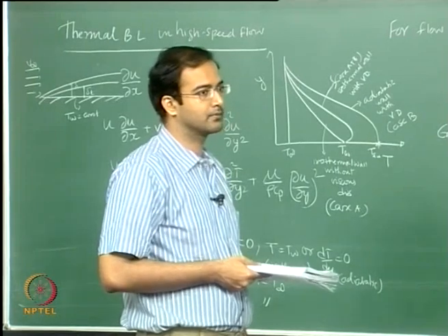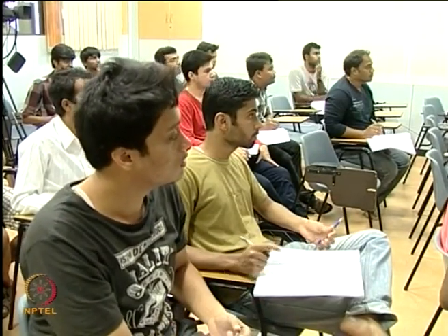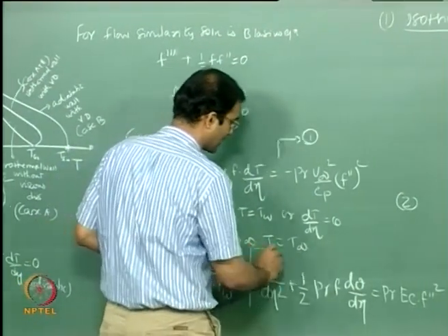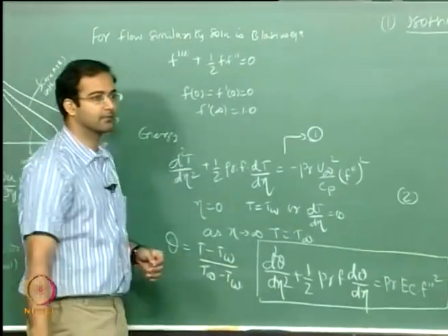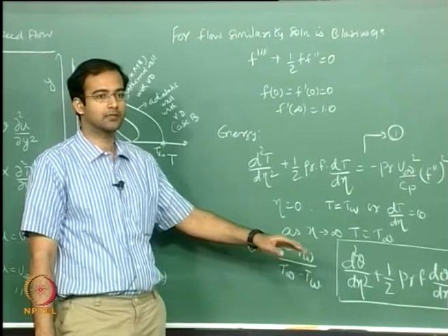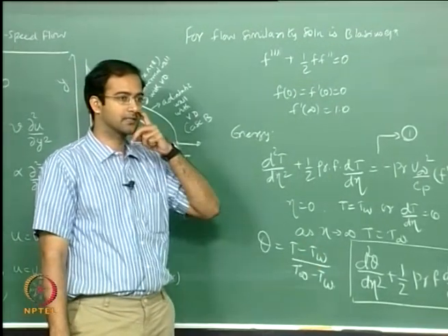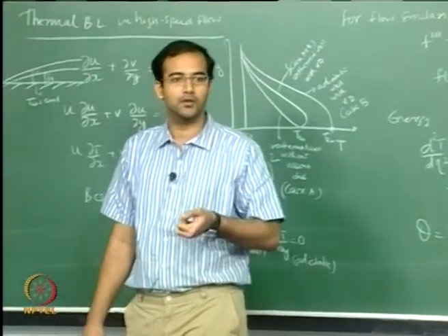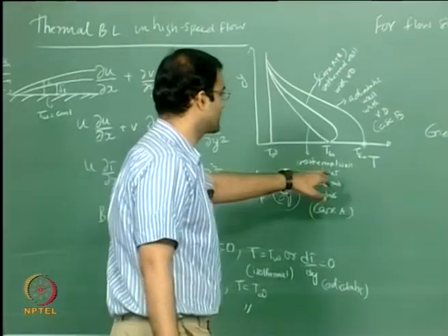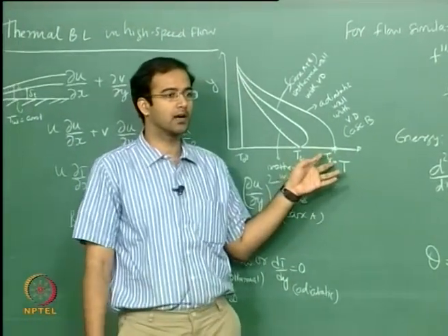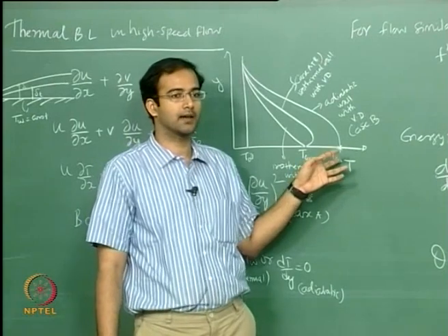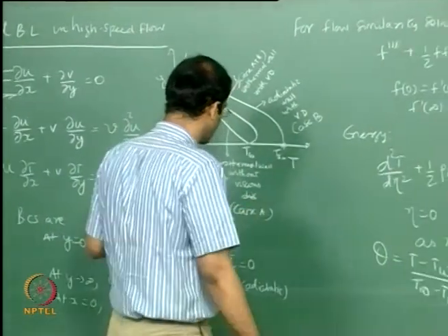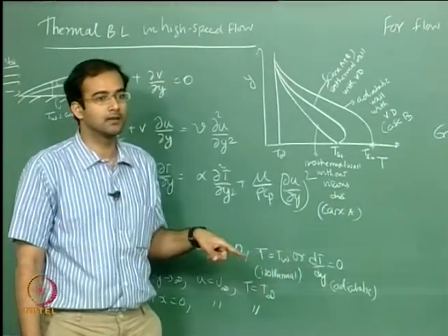Situation, but why particularly adiabatic boundary condition? So what we are trying to say, you can solve this equation as it is. Okay, so this is for the case where you have an isothermal boundary condition with the viscous dissipation. This is what we need, the solution, but we are also interested to know the solution for the adiabatic wall case. We want to actually measure what is the adiabatic wall temperature. So in order to do that, I want to take a case where I have an adiabatic boundary condition with the viscous dissipation, and also the fact that for this particular problem you can linearly superpose two solutions.